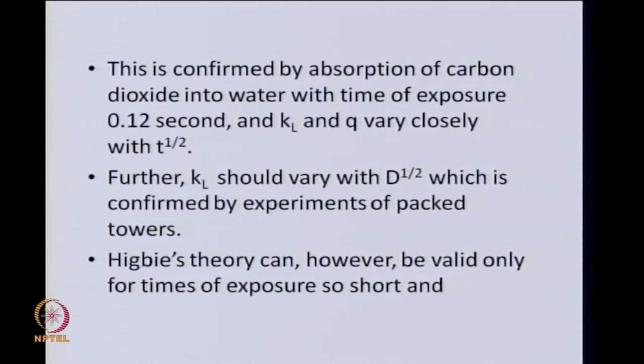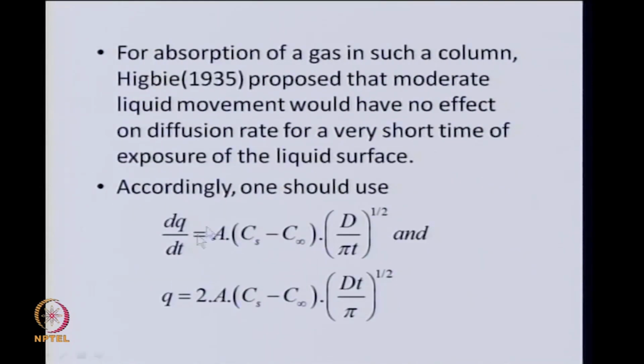And this theory was confirmed by absorption of carbon dioxide in water for a time of exposure about 0.12 seconds, and KL and Q were shown to vary very closely as square root of time as is required in this theory. In addition, KL according to this theory should vary as square root of diffusivity, which is bang in the middle of the observed dependence of mass transfer coefficient in the liquid on the diffusivity, 0.5 to about 0.9.